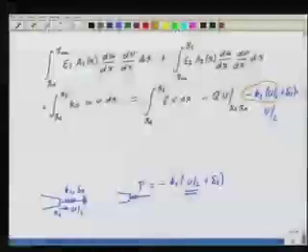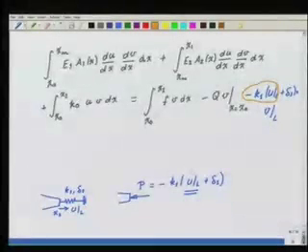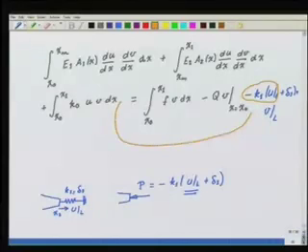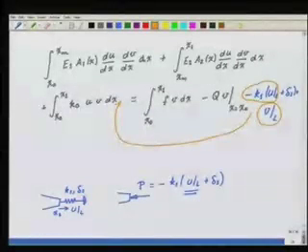Okay. Now this part, minus K1 into U of L, because it is in terms of the unknowns, I am going to carry it over to this side. Okay. And this into V of L, obviously. I am going to leave minus K1 delta 1 into V of L on the right hand side, while this part goes to the left hand side, because we are collecting all the unknowns on the left hand side. Remember this part, because this is going to be important as far as applying the boundary conditions is concerned.